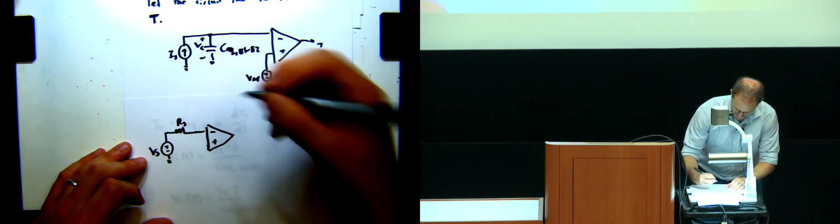Here we're intentionally connecting this op amp usually in this way, meaning that the negative rail is ground and the positive rail is some supply voltage usually associated with the thing we want to read out on the other side to have a nice digital signal telling us if there's a touch or not. So it is, however, very much related to negative feedback. See, that part you had very much in the right direction.